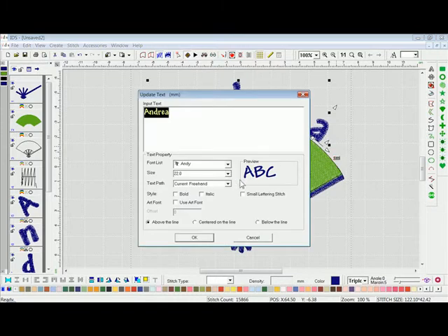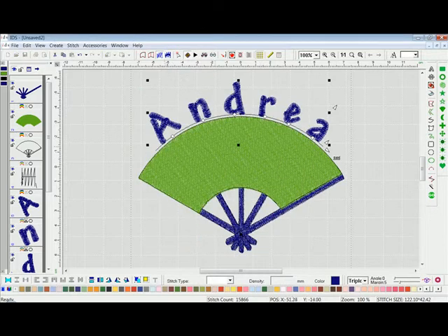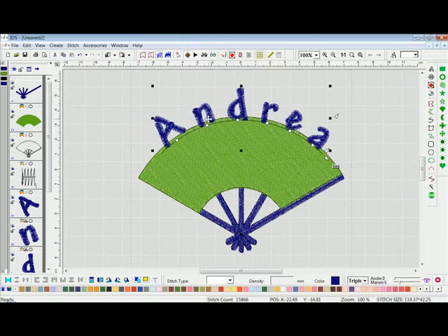We'll go ahead and hit edit. We'll change it from current freehand to existing outline and change that to a -2 instead of a positive 2. We'll press OK, and again we'll start here with a left click. You have to make sure that you're exactly on that baseline. Left click for your other endpoint. When it's blue, I left click and it sits inside that area 2 millimeters. So you can see that it's sitting negatively.